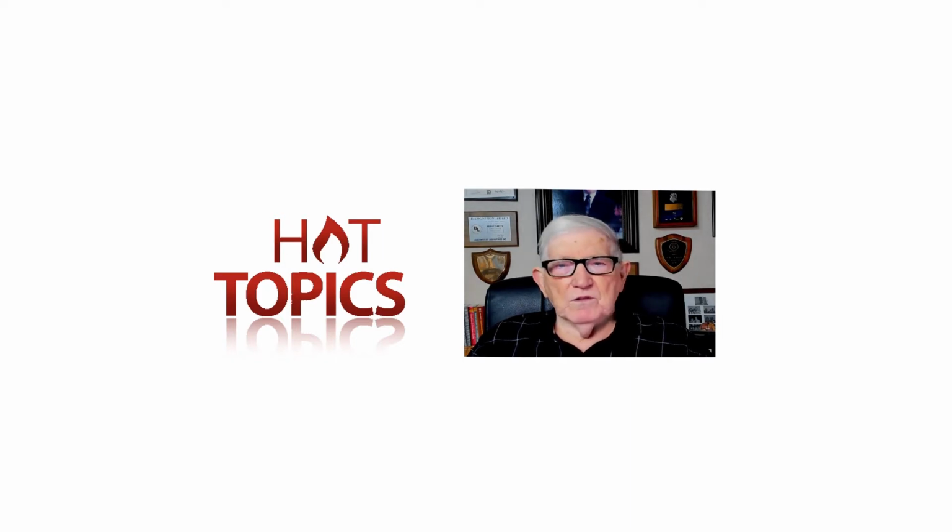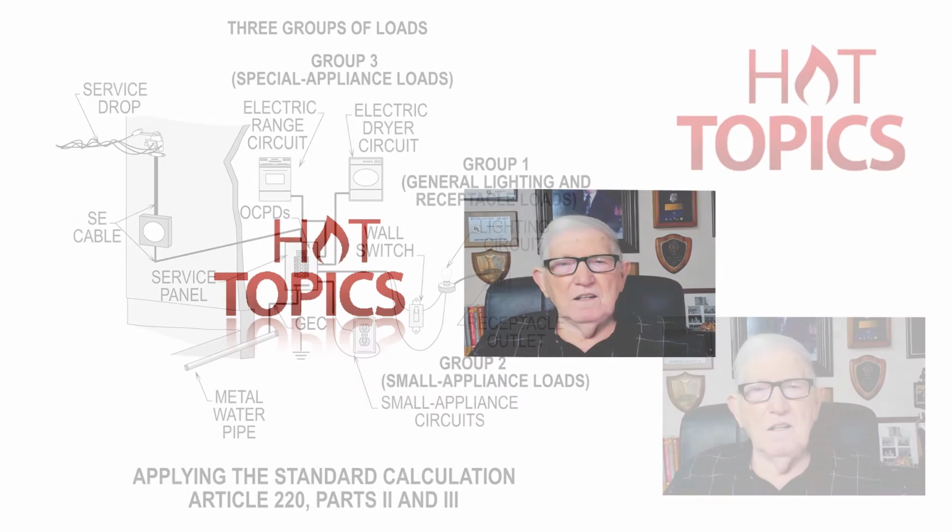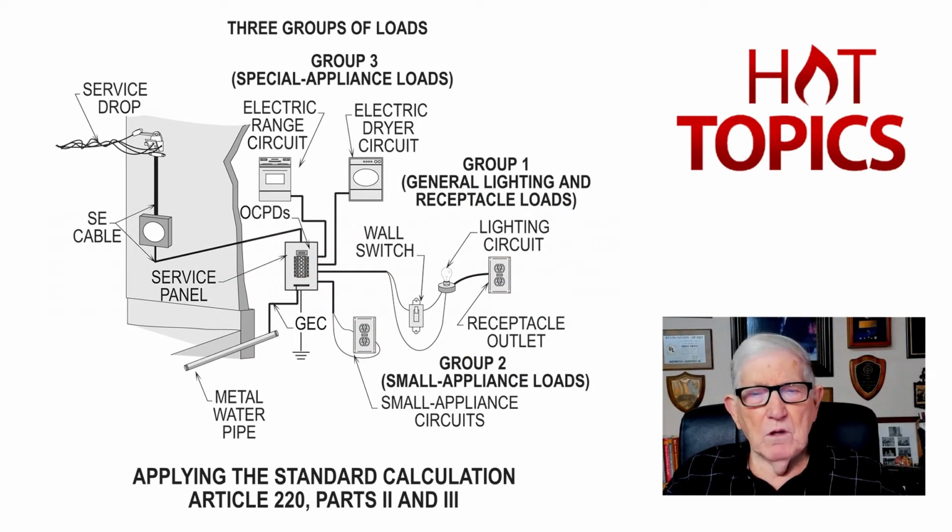And we'll keep these videos coming to you and try to keep you up with the latest as the code changes and so forth. But now notice when we review this particular illustration, we're applying the standard calculation. And of course, you know, Article 220, Parts 2 and 3 deal with a standard calculation. We'll later look at 220.82 and do the optional calculation. But notice we do need to divide these three loads, and that's mainly what we're kind of reviewing right now in this Figure 22-1